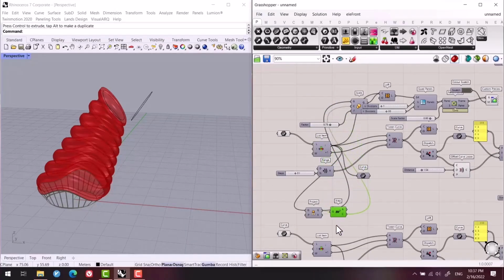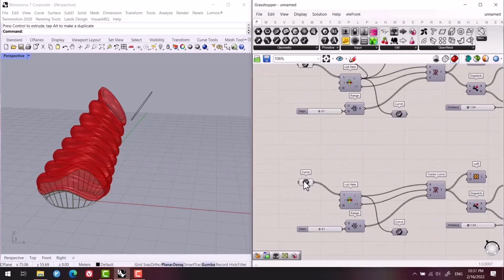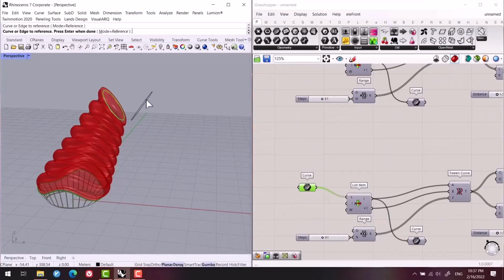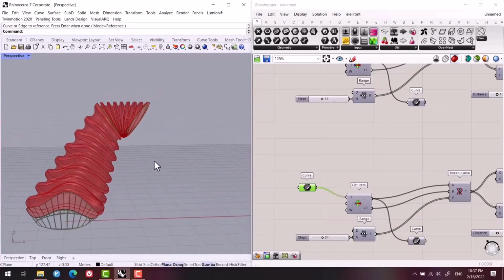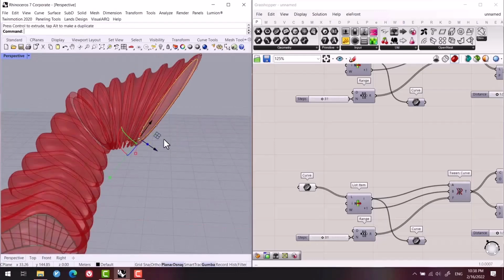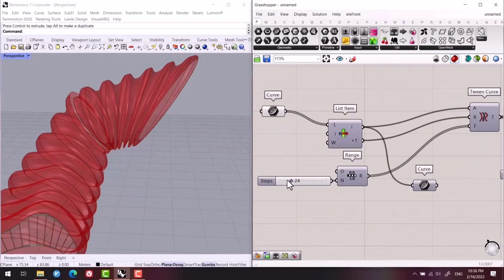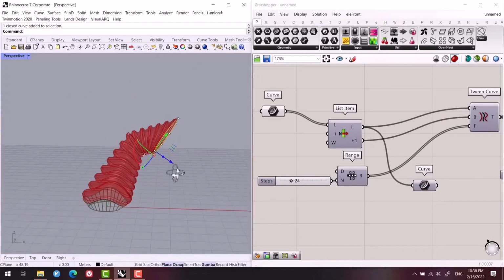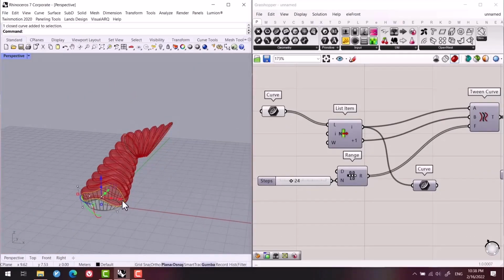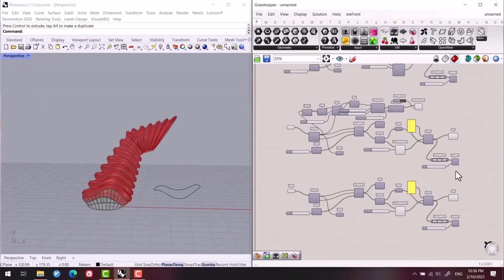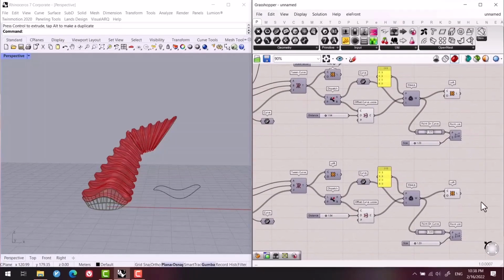Some of them should be moved upward, like project and area for the centroids. So right click, set multiple curves, the two mirrored curves. As you can see, then I want to create a bridge. Let me move the curve. Watch this. And then we can change the range. We can minimize it, for example, as I showed you. And I make a copy from the bottom curve and change the continuity like this.